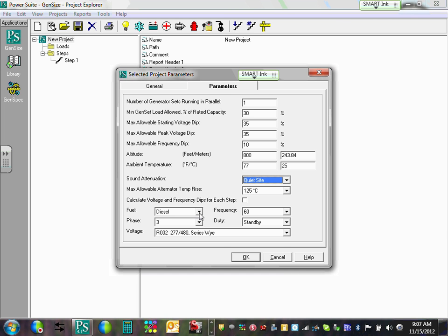The bottom one, fuel. Typically, here's your option. You have propane, you have natural gas, or diesel. Typically, a lot of people, guys, do diesel or natural gas. We're going to do a diesel engine generator. Thumbs up, Chad? Diesel. The phases. Do you think we should do a single phase or a 3-phase for a 3-phase system? Duh, Chad. Your system is 3-phase. What do you do? 3-phase. The frequency, we're in the US, right? So we use 50 or 60.